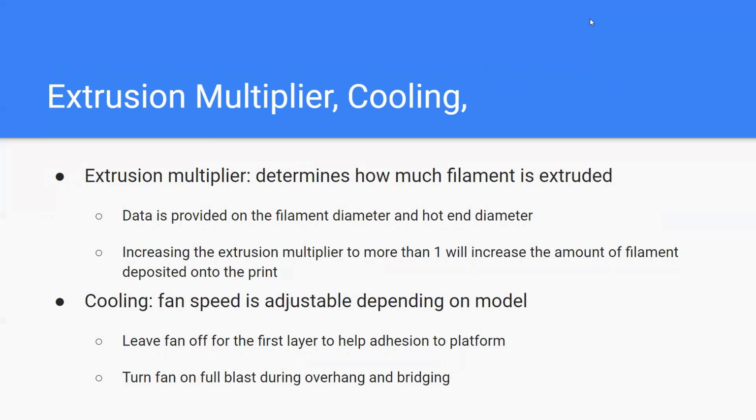Cooling: the fan speed is adjustable depending on the model. You're going to want to leave the fan off for the first layer to help it stick to the platform, and we'll talk about how to make sure you can actually get it off the platform a little bit later. And you're going to want to turn the fan on at full blast during overhang and bridging. You want everything to cool as quickly as possible, because that's going to prevent that dropping down of the filament that we saw earlier.